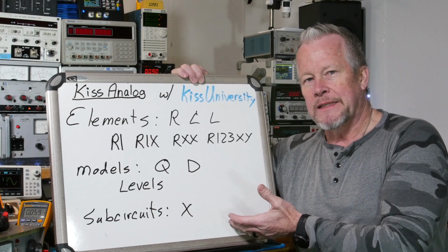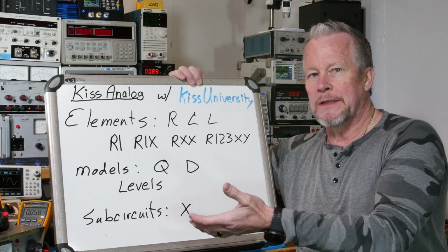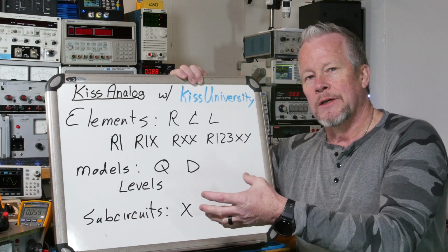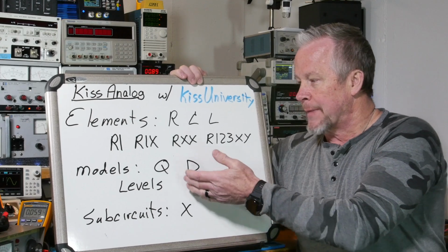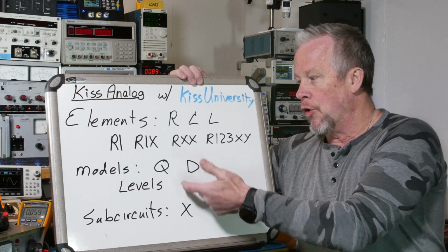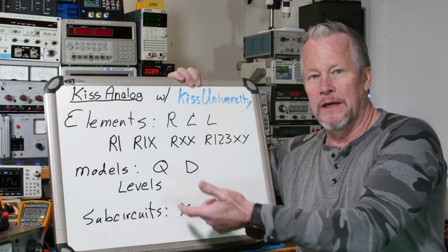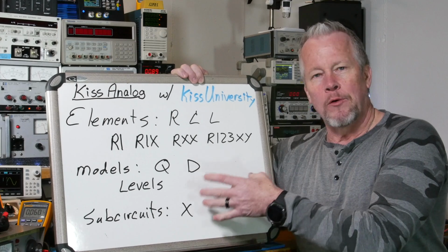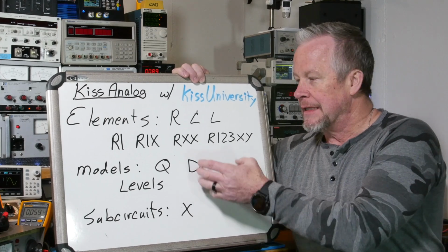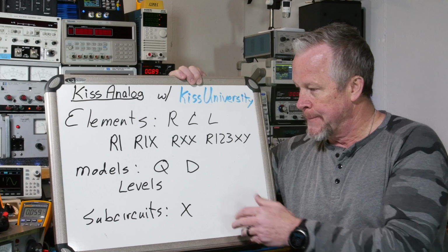Now you might say, well, I want to have the most complex level every time so I get the most correct simulation. The problem is you could slow down your simulation if you have a whole bunch of parts and you're going to level 9 on everything. So some things can be more ideal. They won't really change your circuit behavior, and so you can choose your level, okay?